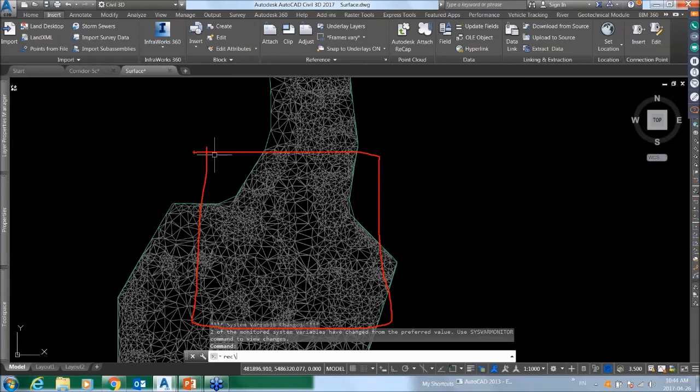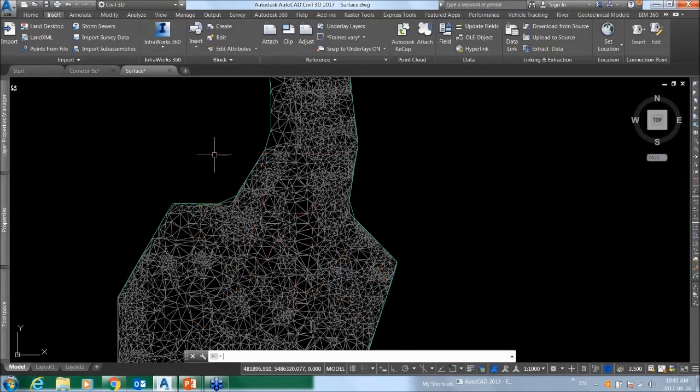When you go to add a boundary, one of the boundaries is called a data clip boundary. If I were to implement that on this data set, instead of having 2.5 million points in my drawing, the only points that would exist are the ones within this rectangle. Maybe it's only 150,000 points. So when you have this large text file with millions of points in it, use that data clip boundary if you don't need all of the points. If you just want a small corridor or a small window, use that data clip boundary.